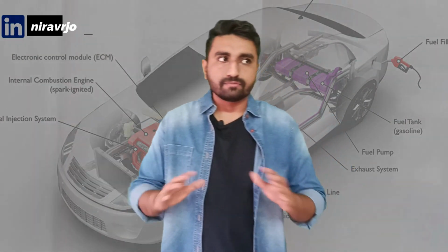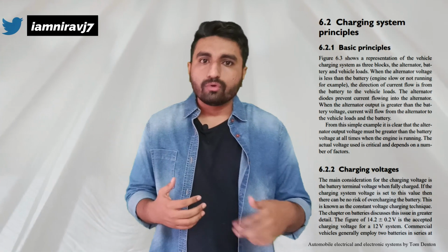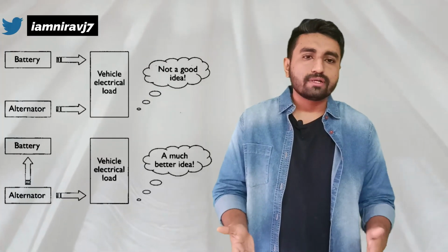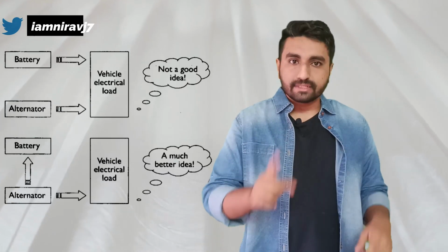See in the charging system, every battery operated vehicle needs to be charged, and most of the vehicles are charged with the help of the alternator. The alternator is connected to the prime mover. The prime mover is feeding energy to the alternator, and the alternator is generating variable AC. This variable AC is converted to DC with the help of the rectifier, and as it is variable DC we need to make it fixed, right? Hence we use DC to DC converters which will fix the variable DC generated at the terminals of the rectifier. So these are the important applications of the DC to DC converter.